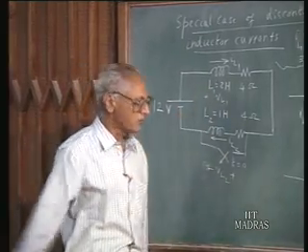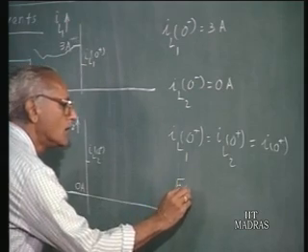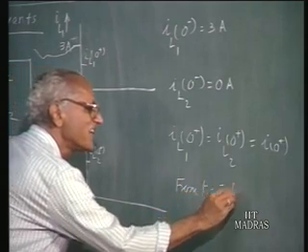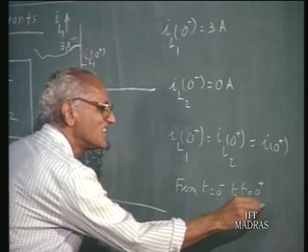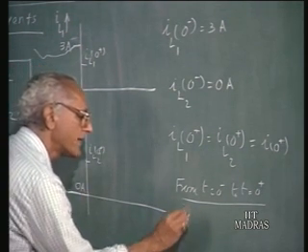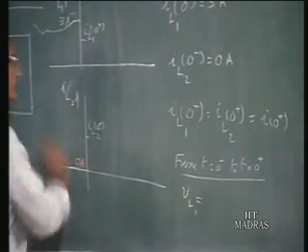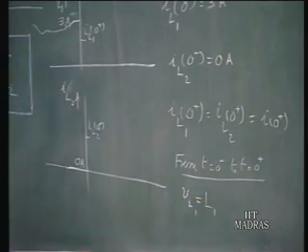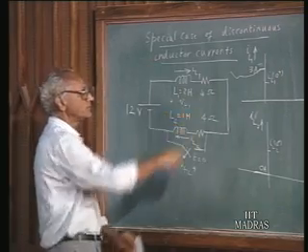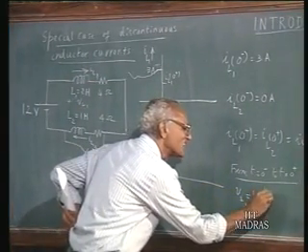So, the impulse in VL1, in the small elementary range of the jump from t equals 0 minus to t equals 0 plus, the voltage across inductance L1 must be described as L1 times the change in current. The current has jumped from 3 amperes to IL1(0+), which is simply I0+.